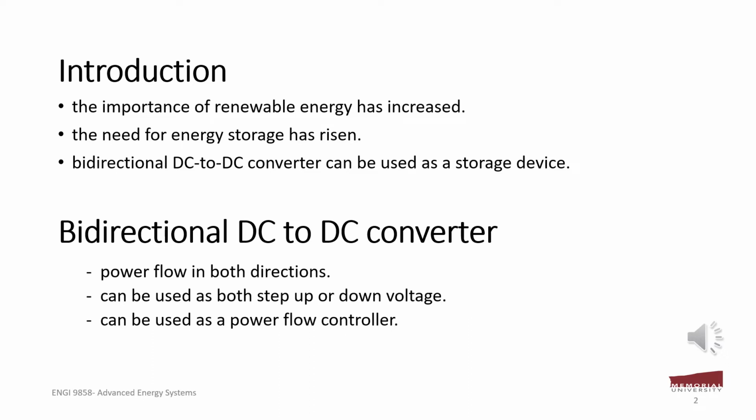With wind energy and solar energy as power sources, the output power is unstable and keeps changing based on environmental conditions. These systems are undependable and cannot feed the system with power due to considerable variation in their output. Therefore, these systems are always connected to storage systems such as batteries and supercapacitors. These storage systems store the excess power when the load consumption is low, and then use this stored energy to back up the system during failures and fluctuations due to weather conditions. So in this case, the bidirectional DC to DC converter is required to permit the power to flow in both directions.